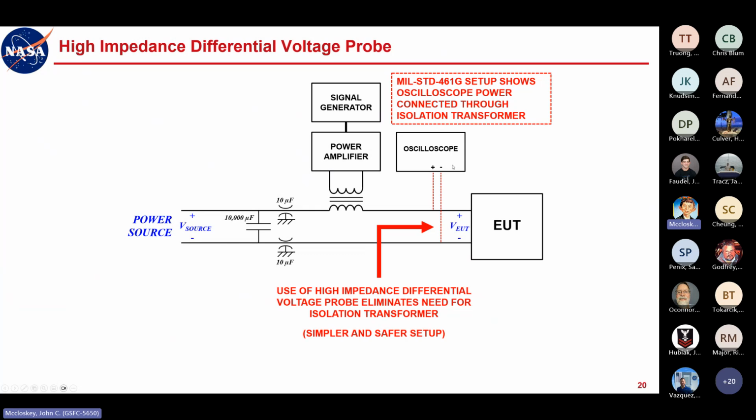And the idea is that, for a standard single-ended scope probe, where the negative or the reference lead is connected to the scope case, you want to float the case with respect to your circuit ground, so that the connection of the scope probe doesn't influence the behavior of the circuit, and it certainly can. So, I mean, it's the right idea, but this may still not work the way you intend it to.